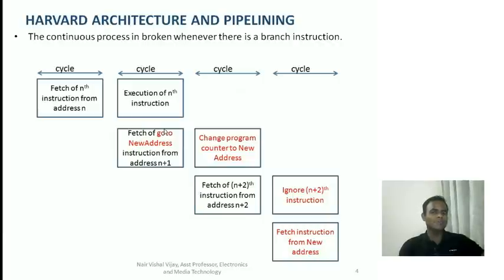That is the time your microcontroller can slow down a little. Whenever there is an interrupt, it will fetch the new address and change the program counter to the new address, once it has dumped the old program counter value to a stack. Then it will ignore the old addresses that were queued up in the instruction pipeline. So that is how it actually processes.